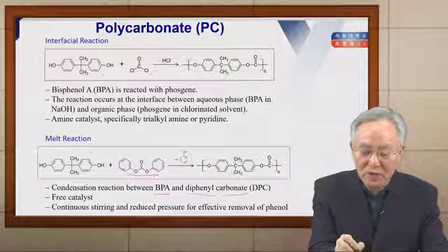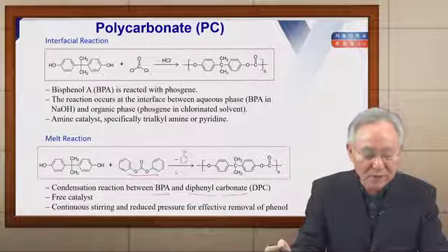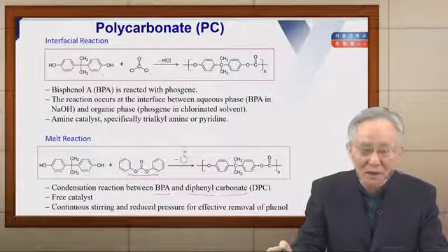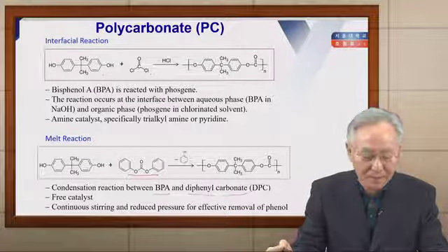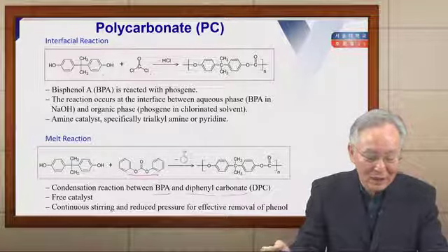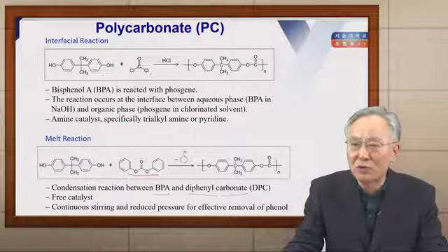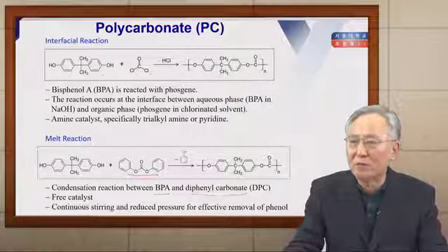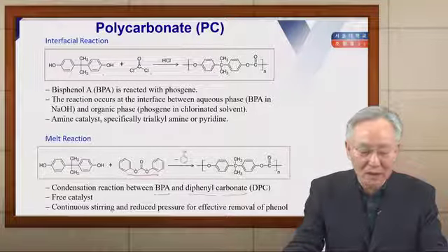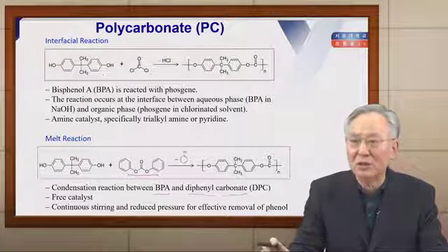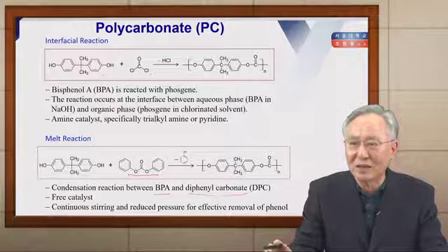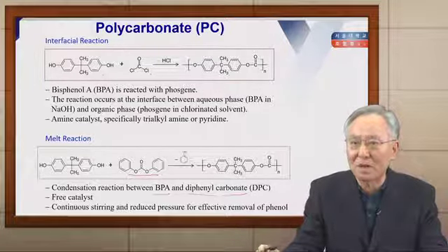So with removal of phenol here, in these melt reactions, catalysis is not necessary. Therefore, just continuous stirring and reduced pressure for effective removal of phenol are required. The melt reaction is commercially available, and most of industry uses the melt reactions.